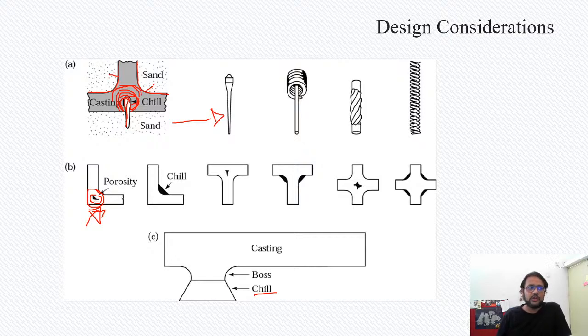So the way you would solve for this problem is you would have a small metal piece, something similar to that fillet line, and then when you cast the whole thing, instead of cooling from just the outside and the center being hottest when it is getting cold, the cooling will start off from the chill also. So it will start off like this, right? And it will lose heat from this side and this side and all these places also, but it would also lose a lot of heat from this place where the chill is put.